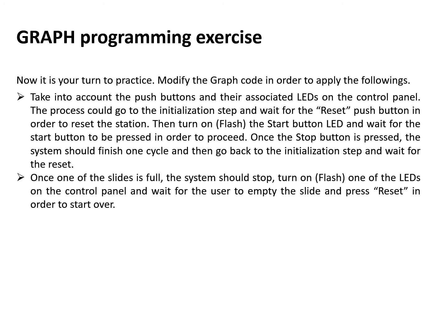Why? Because anyway you are not going to use this program on a real device. But for example, for real inputs, start with I. For real outputs, start with Q. If this is an internal contact or coil, start that with M. Test the program in a PLC sim and please upload it on Moodle.